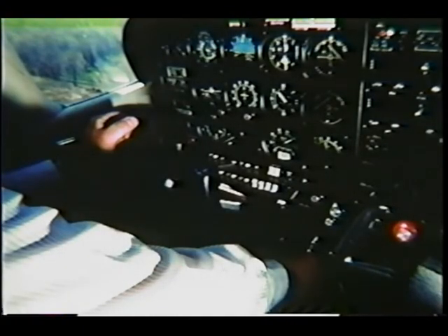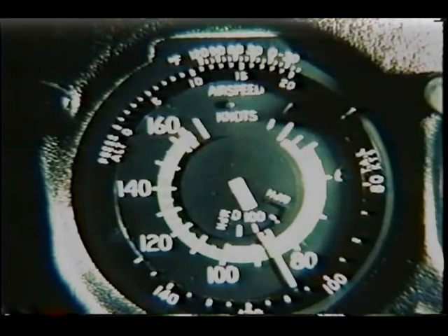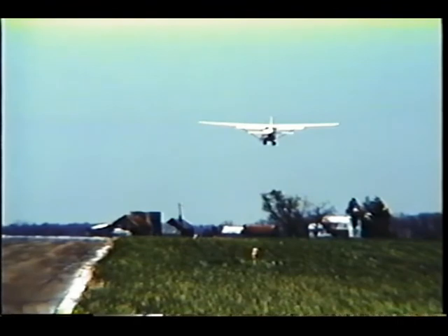Now, once the airplane is firmly under control, ease the flaps back up in increments, further adjusting pitch and trim as necessary, and retract the gear only after a positive climb is established. As your speed increases, let it continue to accelerate past the best angle, then to the best rate of climb. Adjust cowl flaps as necessary, and keep an eye on your track over the ground, staying slightly to the right side of the runway so you can watch for departing traffic.